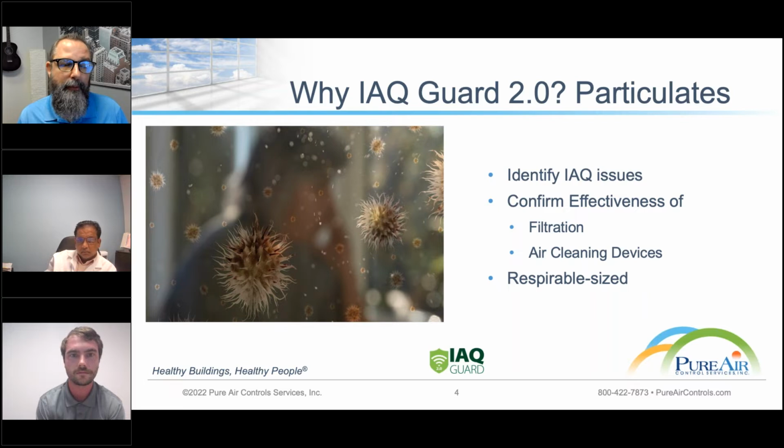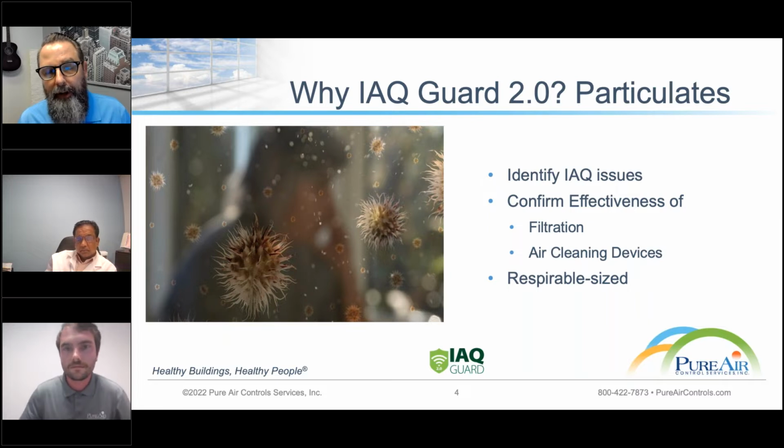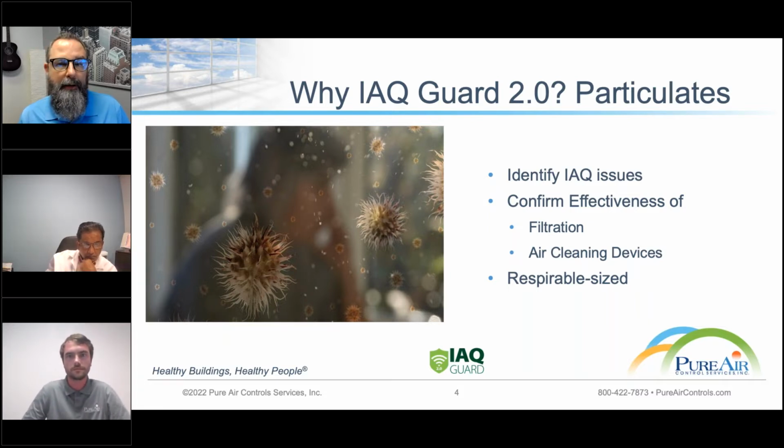Of course, another thing that we look at with particles, right, is that many in-room air cleaning devices have been deployed during the pandemic. So in-room HEPA filtration or multi-stage filters or bipolar ionization. And we can check up on the efficacy of these devices in the room or in the HVAC zone that the monitor is placed in.